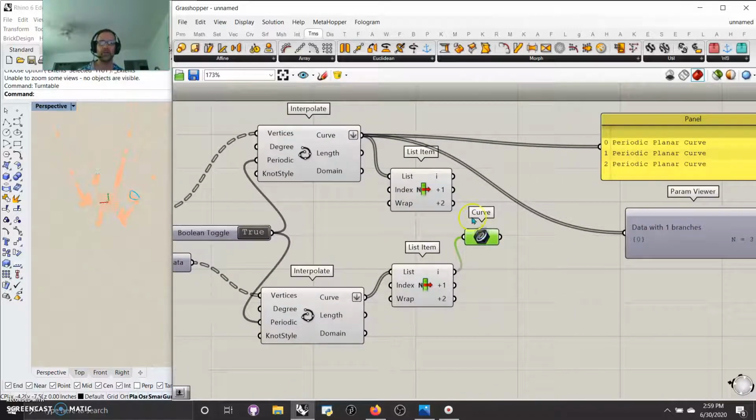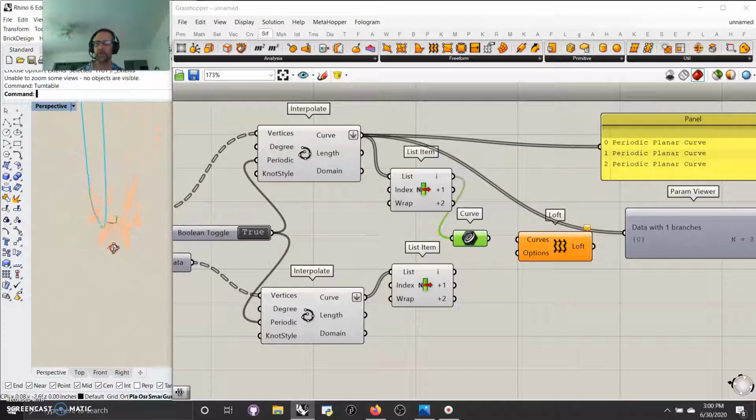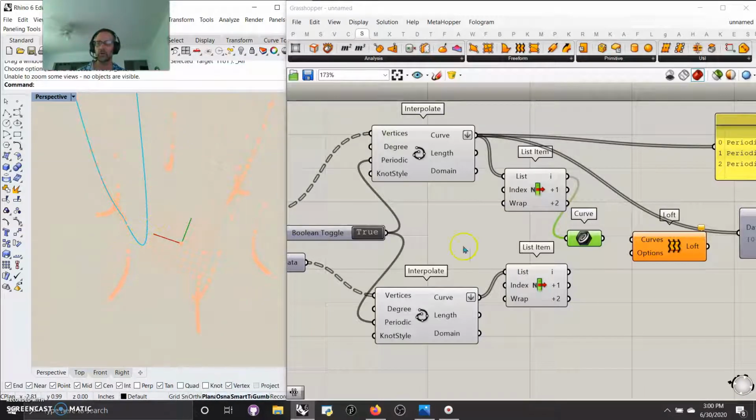So now I have to think, how can I actually loft these objects, because I've been playing with them in that strange way. How can I loft these objects in order? I could use a merge tool in order, but I'm not going to. I'm actually going to put them in order. So if I start with this curve, this big one, I'm going to want one of these small ones on each side afterwards. And I'll shrink this down so you can see it. So I'm going to want this one next or this one next. So I'm going to put that one in. And with shift, I'm going to take a look at, well, without shift yet, I don't want that one. I could use this one. I'm going to hold down shift and put that one in next.